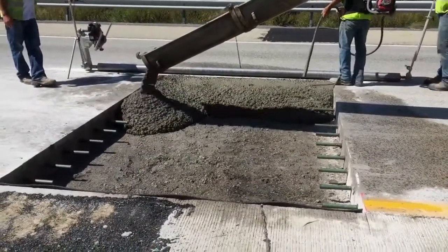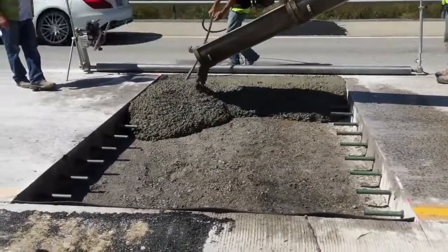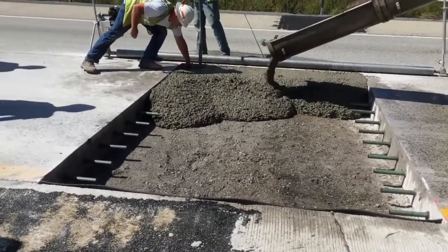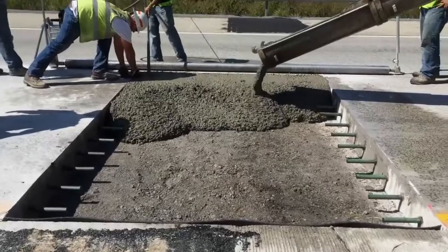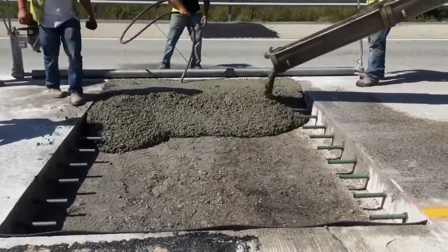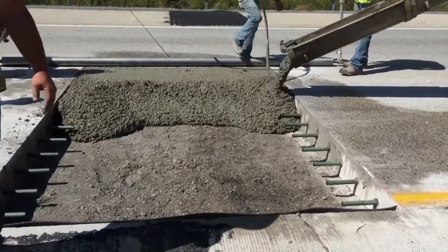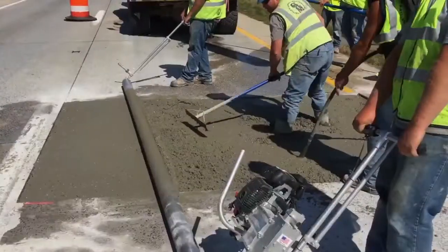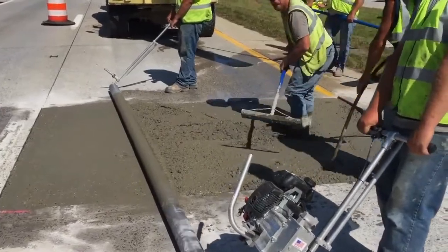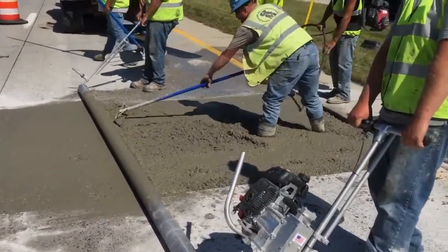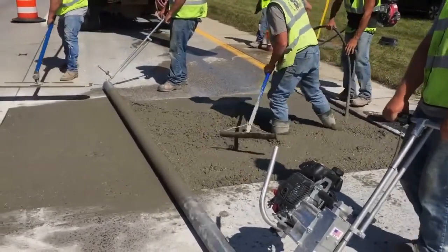Consolidation of the concrete using a vibrator is critical. Care must be taken to not over-vibrate the concrete. Carefully vibrate the concrete along sides, around dowels, and in the corners of the repair area. Do not use water in the aid of finishing, as this could cause the concrete to fail prematurely. Use a roller screed parallel to the center line of the pavement in a transverse direction to ensure that the concrete surface is flush with the adjacent concrete.